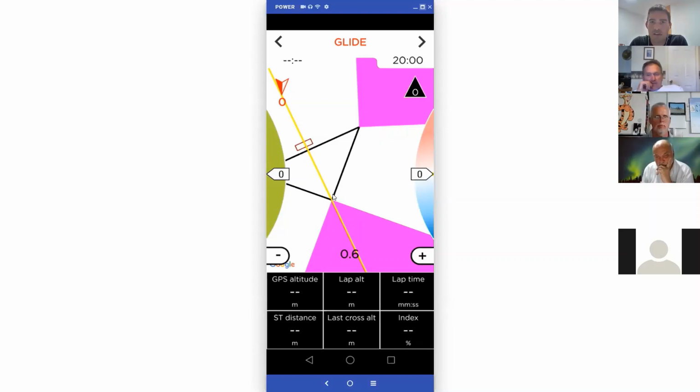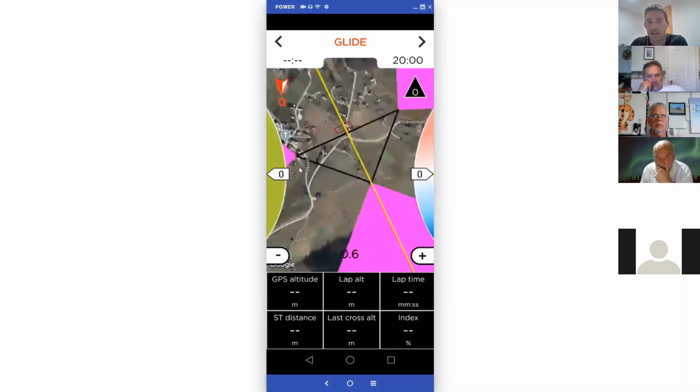When you have the airspeed, it doesn't matter if there is a wind or no wind. You just have to fly your best LD speed to do the most triangles. If you check the ground speed, it will not be okay when it's a windy day. If it's no wind, you can use that. But when there is wind, if the wind blows from this direction, you will fly very slow this leg and very quick this one. So basically you would like to go slower here, but you will stall because you have a higher ground speed, but your true airspeed is what really matters.